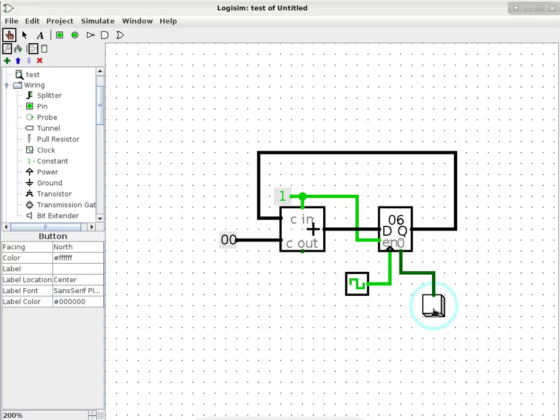By using a register in between the output of the adder and the input of the adder, now you can say, when do I want to update? Should I update? When to reset it back to 0? Now you have full control over the counting process. So are we doing okay so far with this little circuit here? Okay, very good. Let's see, how much time do we have?